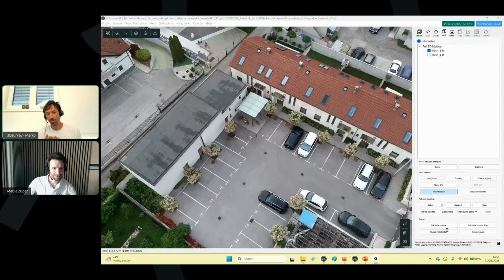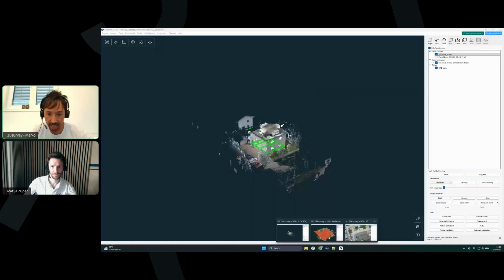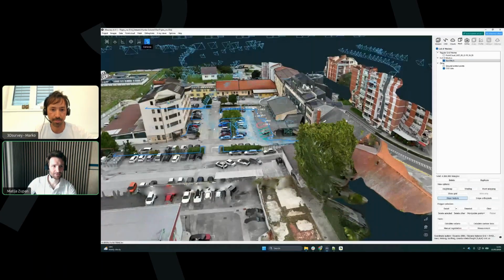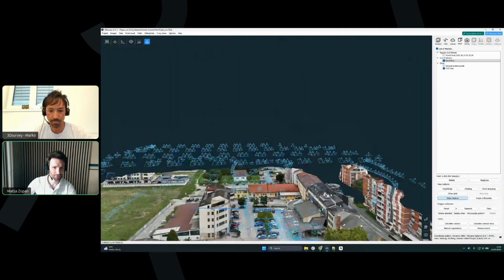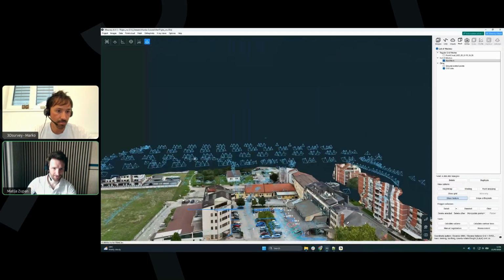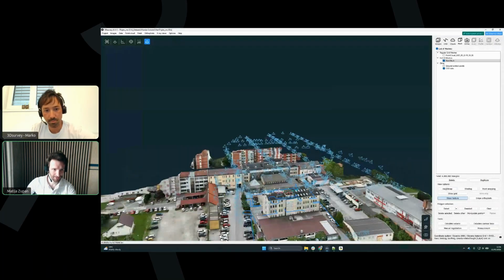So if you have opportunities, trigger more images from different perspectives. The more images from different perspectives you have, the greater the mesh result will be. So you can go really, really detailed. So yeah, if we check here, let's start from top down. First there was sort of a grid mission, just going around with the drone. Then there's an ellipse or semicircles around the building.